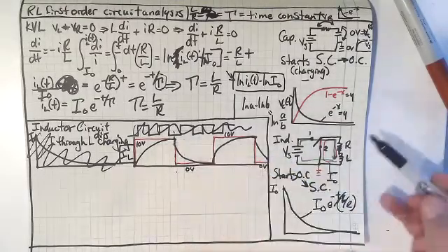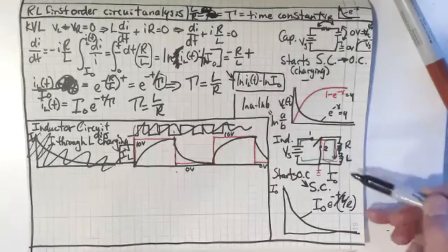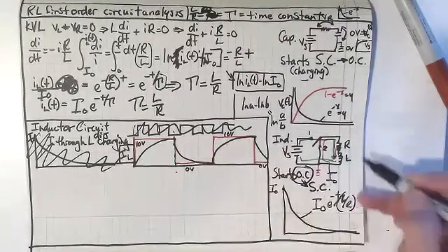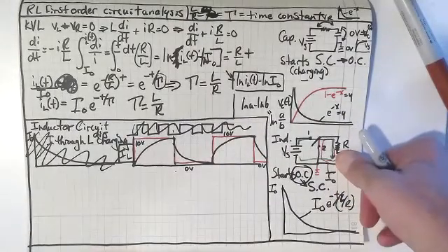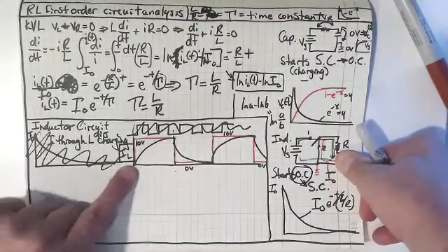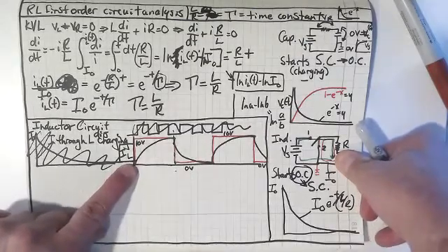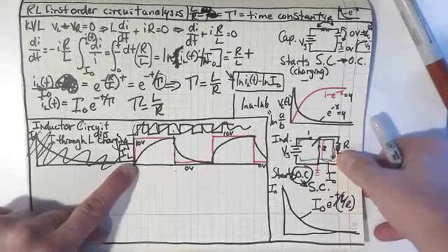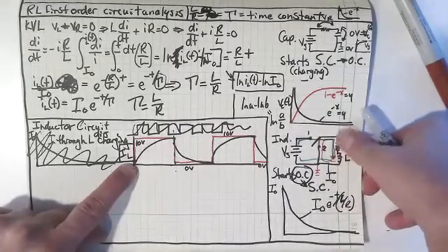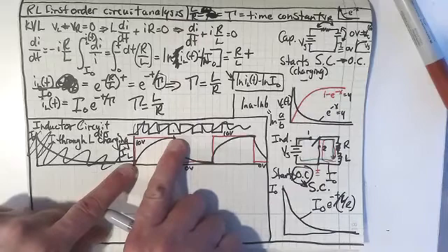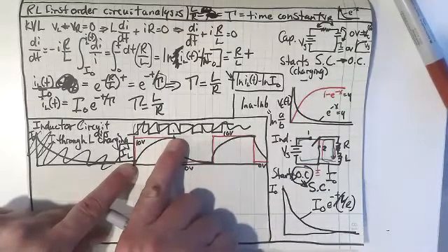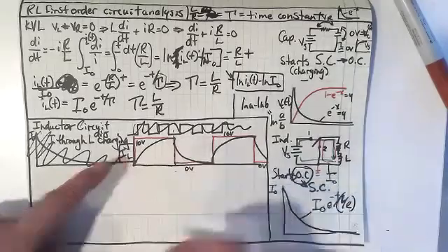And what's happening is this starts out as an open circuit. So if this is an open circuit, let's just take that out of there. Is there any current flowing through that circuit if that's an open circuit? I think everybody sees that there's no current flowing through it. And so the current then is going to be 0. But after a while, that thing becomes a short circuit, doesn't it? So then all of the current is flowing through that circuit, as much current as we could get.